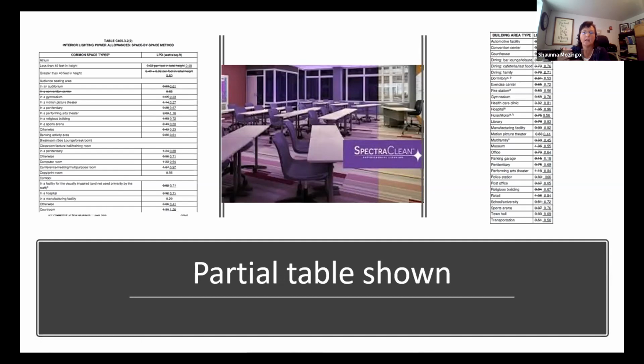While there are a variety of strategies for permitting and obtaining a certificate of occupancy in core and shell buildings with unfinished spaces, we are concerned about one scenario in particular, where tenant spaces are provided with minimal lighting to meet the egress requirements of the IBC so that a permit can be closed out, with the intention that this lighting will be replaced when a tenant leases the space and does their own fit out with permanent lighting.